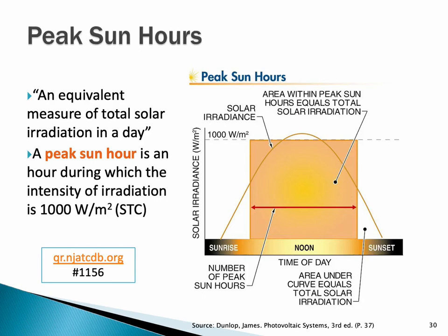Or in the summertime, we could say over 6 hours we have 1,000 watts per meter squared, or 4 hours of 1,000 watts per meter squared, and it's a cumulative over the course of the day. And we've seen this peak sun hours, or the average sun hours, I should say, when we messed around with PV Watts and looked at the average sun hours for the year.